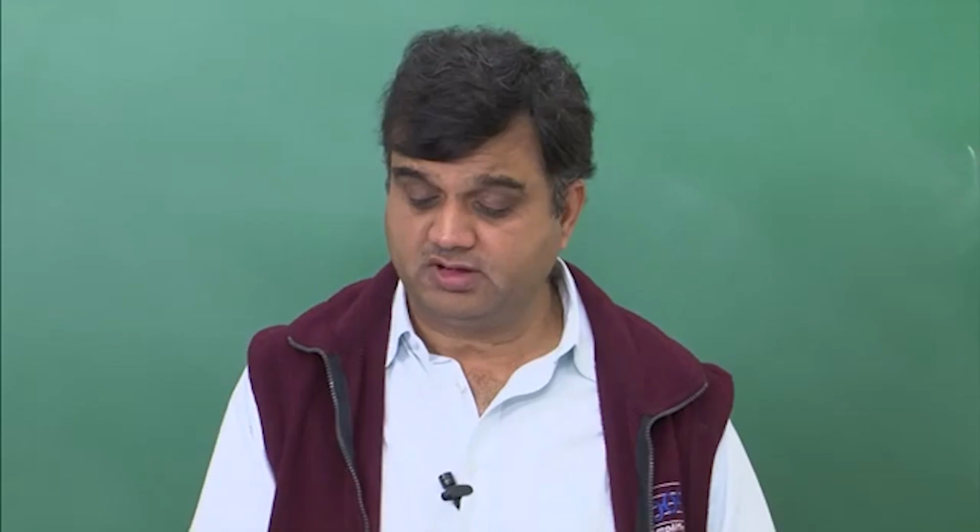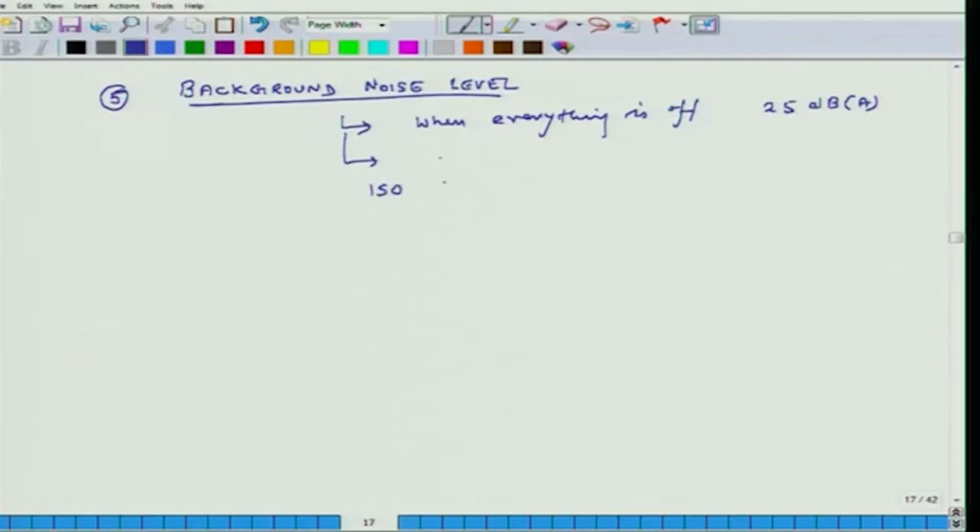There are some ISO standards to verify these things. So one ISO standard is 3745, and then there's also 140-4. There are some standards, okay. And what these standards say that, okay, inside noise level is going to be 25 dB, when outside noise level is 70 dB, okay. So they always characterize in context of what is the noise present outside. So that is important. Okay.